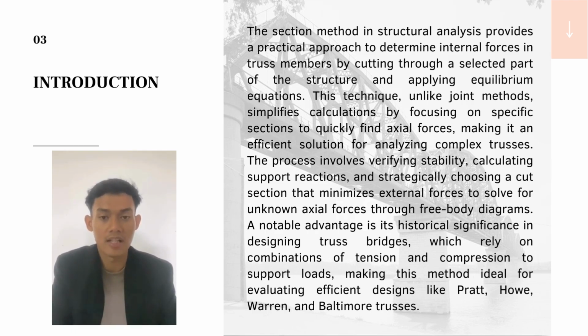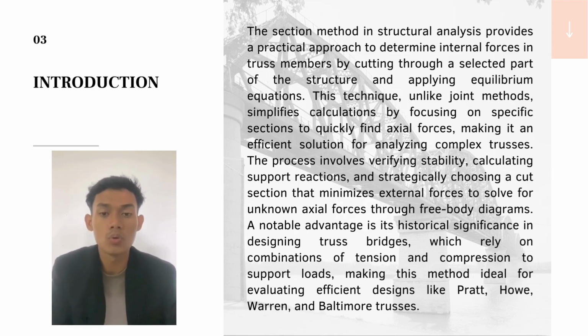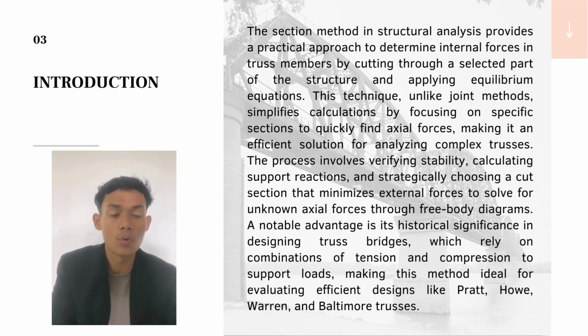Next, for more explanation, the process involves verifying stability, calculating support reactions, and strategically choosing a cut section that minimizes external forces to solve for unknown axial forces through free body diagrams.